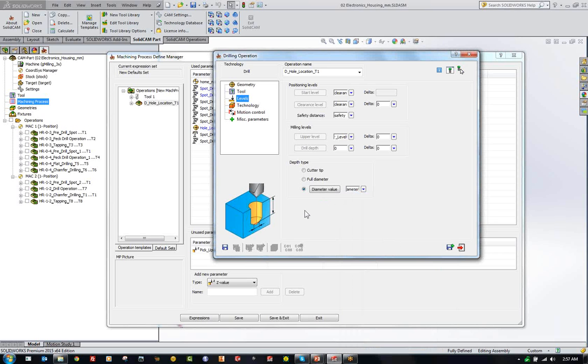Now, I haven't gone full depth into this and created that value to be plus or minus or checked on whether or not, if the upper countersink exists, we're going to use it, else we're going to use something else. So you can create all that logic in there, and then you can use that inside here. So sometimes a variable that you create as a user variable can be used in multiple places, maybe even in different fashions, different equations applied to it, but that same variable can be used for others.